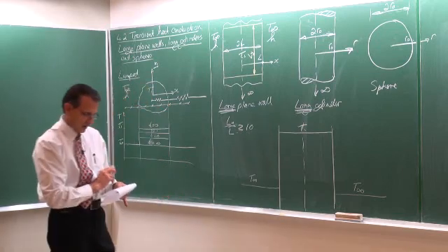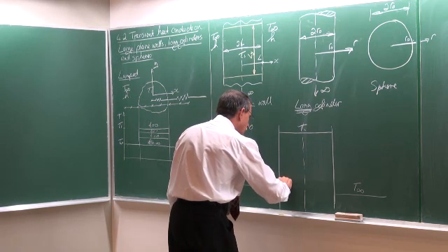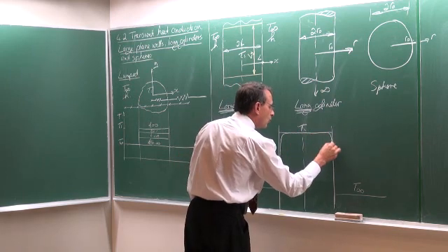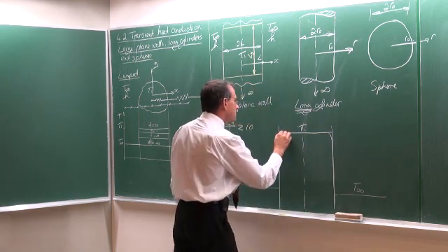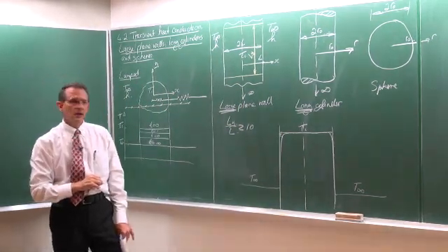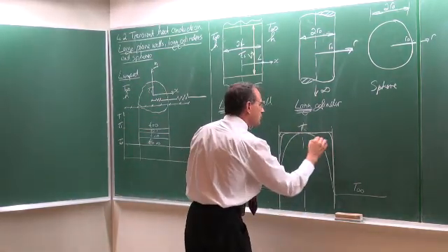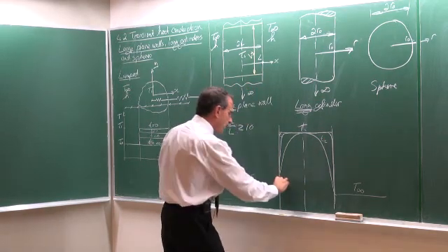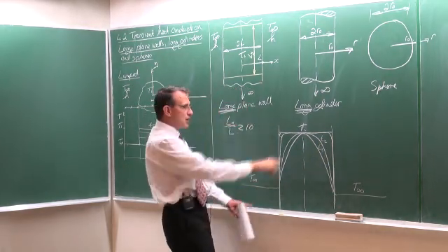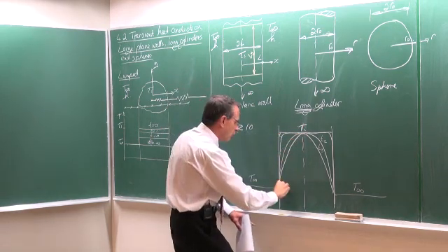Now, at a small fraction of a time after t equals 0, if we would take temperature measurements through this plane wall, it's going to look like something like that. So that would be T1. And then the temperature distribution would start looking like that, T2, T3, and then after a while, this temperature in the center will not be equal to the initial temperature anymore.